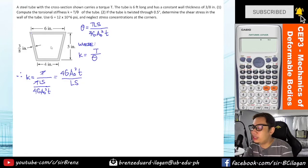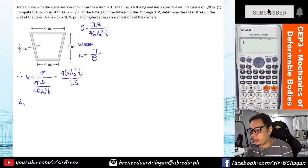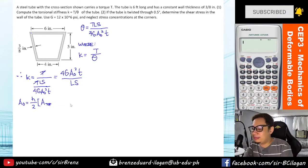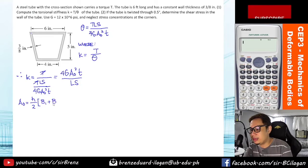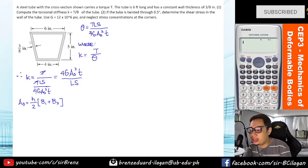So what we will do in order to solve this area: this is just the area of a trapezoid. If you remember, what is the area for a trapezoid? The area enclosed, or A sub O, is H over 2 multiplied by base 1 plus base 2. Since the given measurements are at the middle, not end to end, we no longer need to consider the 3/8. That is only for the thickness T.